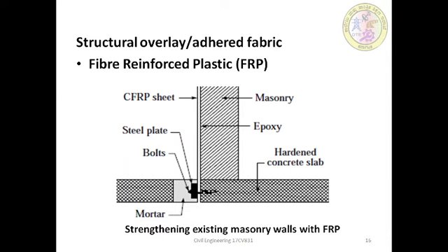There are various examples where FRP has been successfully used for the retrofitting of RC structures. The use of fabric materials like carbon fiber reinforced plastic, usually called CFRP sheets, and glass fiber reinforced polymer, usually called GFRP sheets, are the latest developments as a medium of retrofitting of RC structures. The method of strengthening unreinforced masonry walls with FRP is quite simple and rapid.